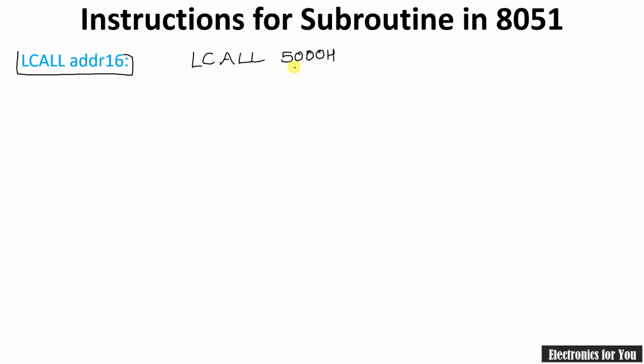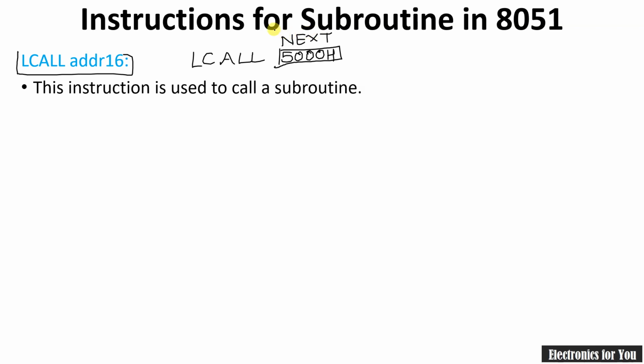It simply means that the program execution will call the subroutine which is stored at the 5000H memory location. But actually in case of 8051 programming, we use some label to indicate this address. Let that label be NXT here. So LCALL is used to call the subroutine.